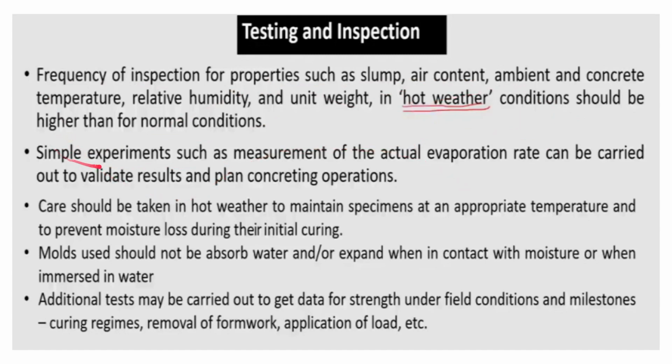Simple experiments such as measurement of the actual evaporation rate can be carried out to validate results and plan concreting operations. This is a very simple experiment which can be done anytime. It can be used for validating our plan and making it more efficient, and for planning the concreting operations accordingly.